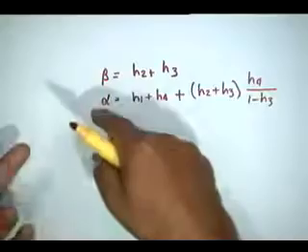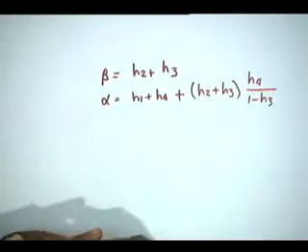Suppose you have h5 z to the minus 5. Take 1 there, all right. Then the rest you can tap it out. Only thing is, you shall have to use a little more calculational effort and perhaps one more multiplier. Okay? But that may be compensated by the reduced number of multipliers in the linear phase term.